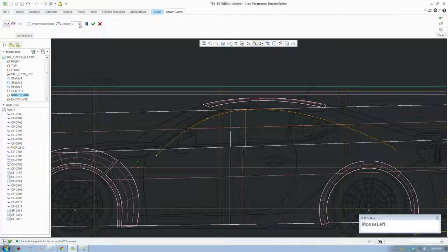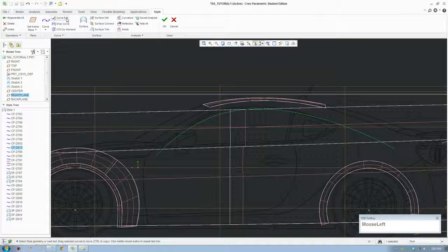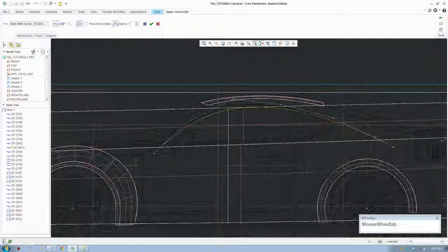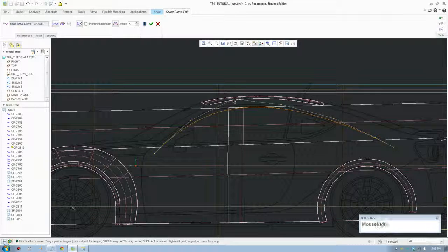This line is quite complicated, and usually you want to put on 5 degrees for a curve that's not just fairly straight but fairly curvy. So it's just a tip that I learned, which will be helpful. It just makes your model look better. So I'm just testing it out. So just use 5-degree curves for complicated curves.